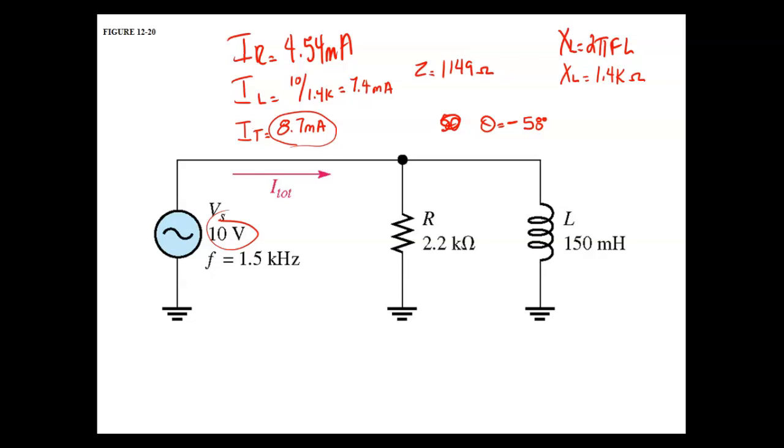So that's why Alabama Power charges these companies a penalty if they run a power factor less than 95%. And then they step it depending on what your power factor is. So these big companies definitely try to figure out how to monitor that power factor, right? And not only monitor it, but figure out ways to correct it. So what's one way we can correct it if it's inductors? We can add what to the circuits? Capacitors. Yeah.